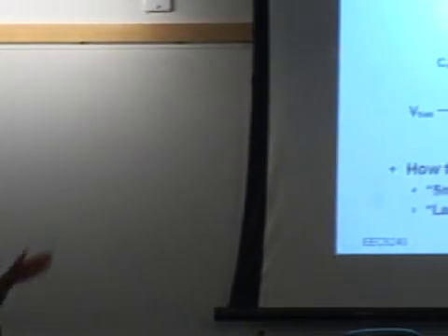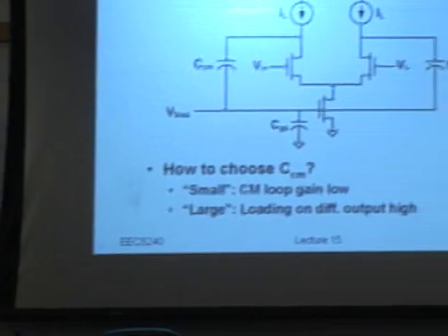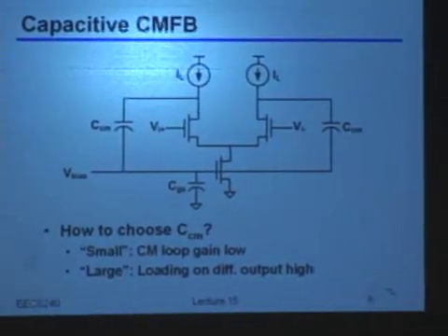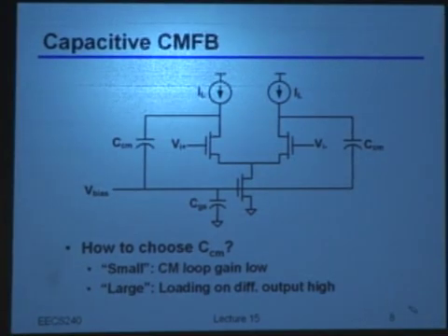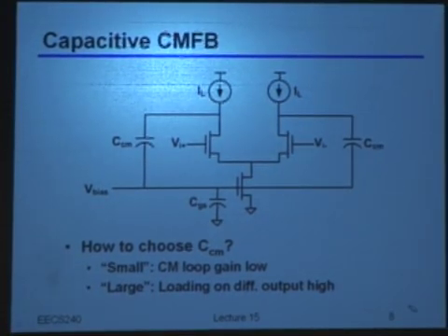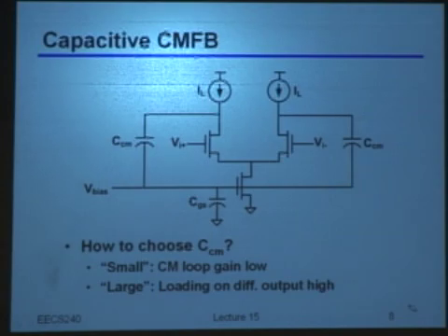First of all, let's catch up on where you were, about capacitive common mode feedback. I think Elad told you why we like this topology. We also want to use capacitive sensing for this common mode feedback configuration. That's precisely the same reason why we use capacitive feedback in switched capacitor circuits and normally in integrated circuits, so it's not loading too much the amplifier.